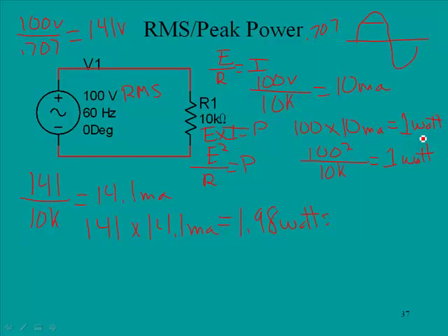As I said, RMS is pretty much the standard. Sometimes you'll see peak ratings with manufacturers of audio equipment, so they try to make their product look a little better. So be very careful when you evaluate the power on amplifiers and whatnot.